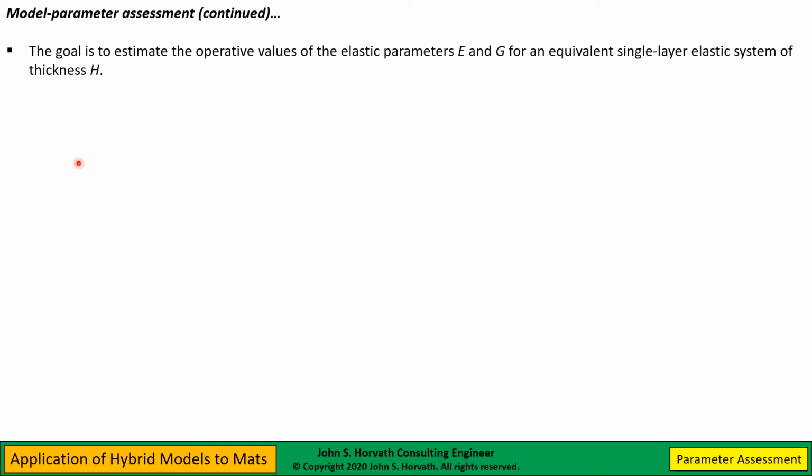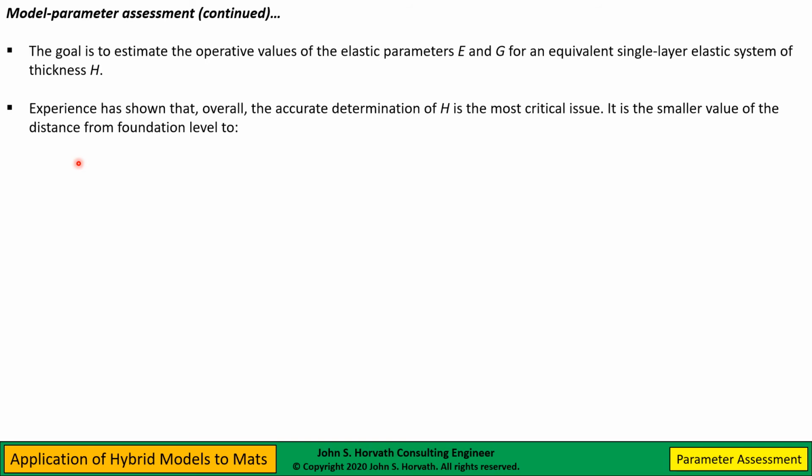So the goal is to come up with operative values of the elastic parameters for this equivalent single layer elastic system of artificial thickness H. Now, I found, after using this for a couple of decades now, that really the determination of H is the most critical issue here.